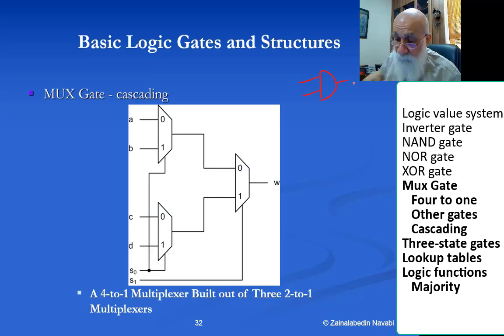Let's look at a 2-input AND gate. If you want a 3-input AND gate, this is how you do it. If you want a 4-input AND gate, this is how you do it. For a 5-input AND gate, you can just put AND gates, and easily cascade them. But for a 4-input, it's better to do it this way, because the other way you have a long path from some of the inputs to the output, whereas in this case the worst-case delay path from the inputs to the output is more balanced.